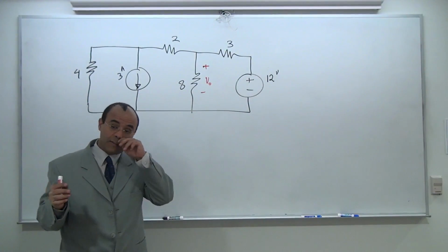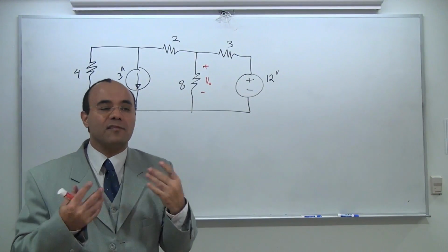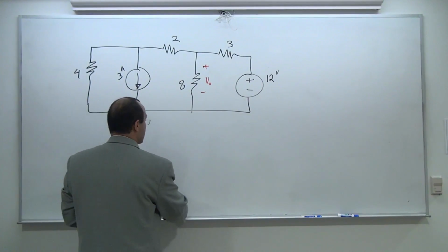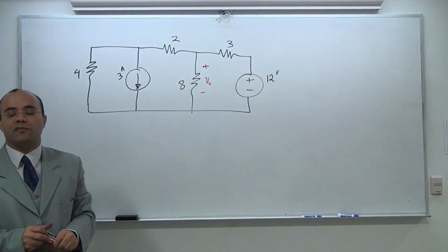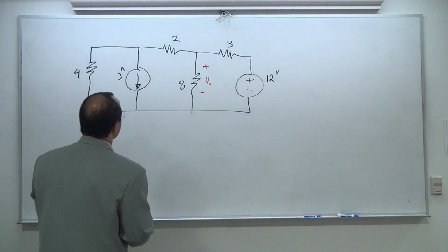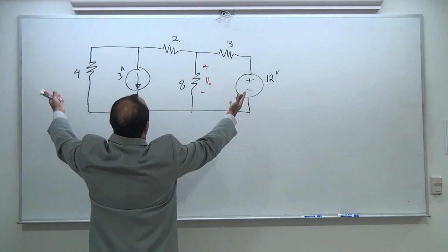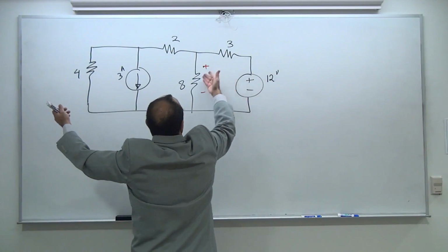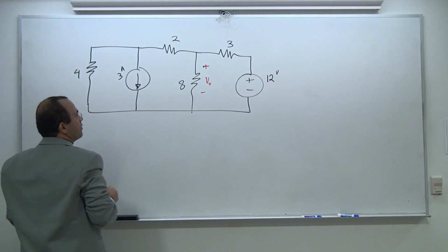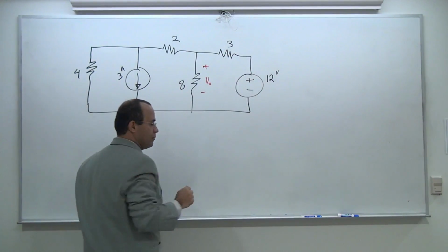So these are different techniques. We are simply considering the circuit, analyzing the circuit in a different light. This time, it's source transformation. Why do I want to do source transformation? You see, right now, I can't see myself. Are these in series? No. Are these in parallel? No. These two are in parallel, of course. These two are in series, yes.